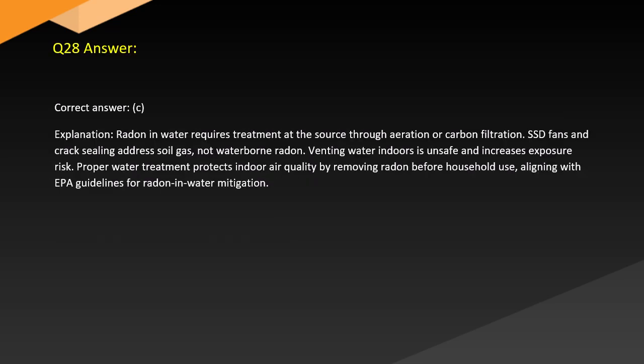Answer. Correct answer: C. Explanation. Radon in water requires treatment at the source through aeration or carbon filtration. SSD fans and crack sealing address soil gas, not waterborne radon. Venting water indoors is unsafe and increases exposure risk. Proper water treatment protects indoor air quality by removing radon before household use, aligning with EPA guidelines for radon and water mitigation.